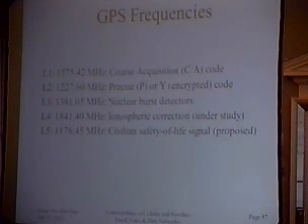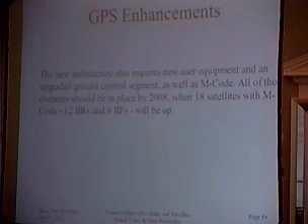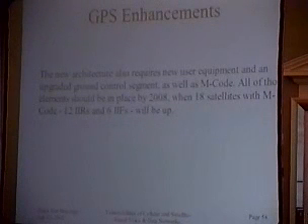So what they suggested was, let's send another signal at a higher frequency and we'll be able to even out the issues with the ionosphere. And they're also talking about L5 as a way of getting even more GPS accuracy. As the military is looking at what they're going to need to do in the next few years, the next follow-on program is something called M-code. M-code will be an encrypted signal that will address some of the shortcomings that they found so far related to jamming and spoofing.